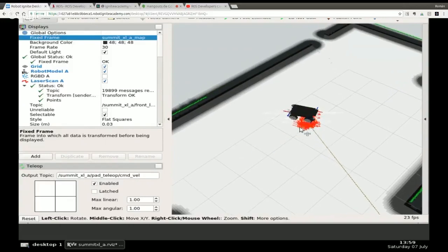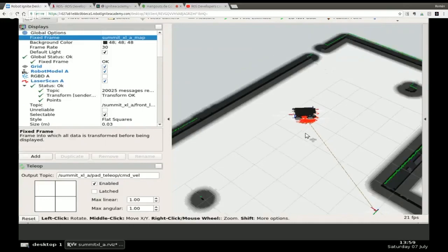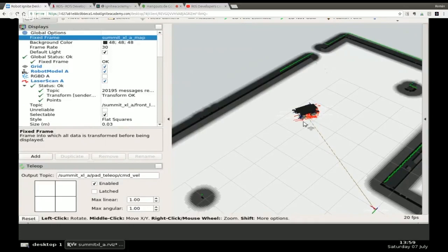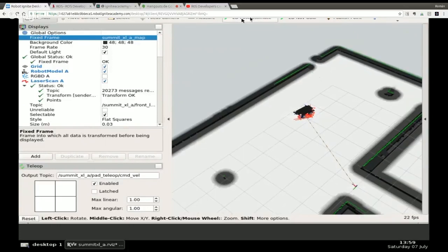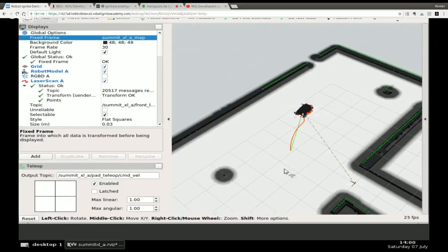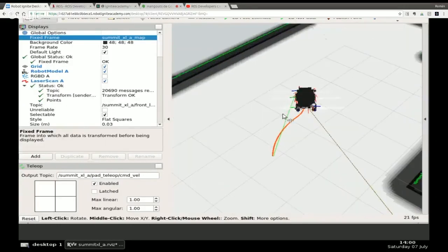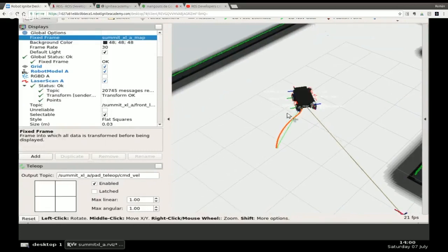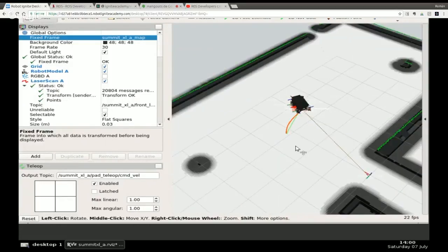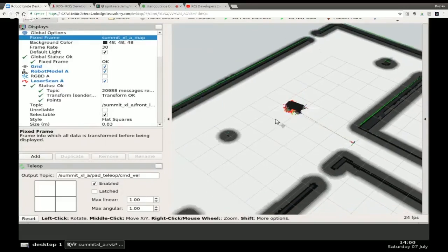As it is an omnidirectional vehicle, the movement is going to use X and Y. And so with move base, we are setting a position and orientation of the robot. You can see here the final position and the final orientation. These markers that we will see later are for the path on the cost map.